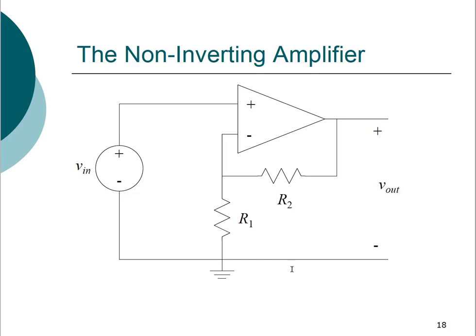An op-amp can be used as a non-inverting op-amp when the supply is given to the positive side of the op-amp. So you see here the supply is given to the positive side of an op-amp, and the feedback is provided through this to the negative side. Okay, so in this case, your output is not inverted, and that's why it says non-inverting. So whatever the direction of the input is, in the same direction you'll get the output signal, and the signal will not be inverted, but the signal will be amplified value you will get at the output.